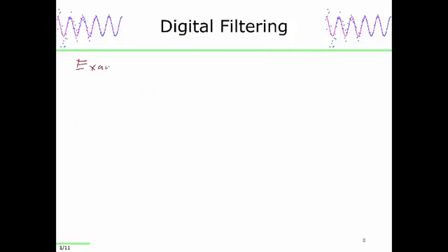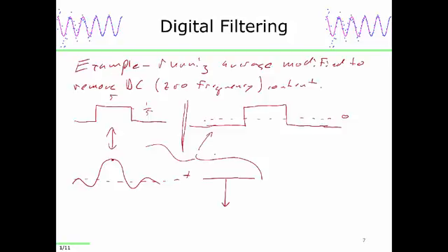How is the impulse removing the DC? So the question, well, okay, let's go over this a little bit. I'll give you a better example in the next slide, because this one's a little tricky. Because the time domain response is constant to begin with in the rectangle, and I'm subtracting off a constant, which would just give me 0, which would be nothing. So I have to make it longer such that the average of the digital filter is 0. Why would that matter? Because let's say I had a constant term, a background term. If I sum up every element in this digital filter and it equals 0, and I multiply that by the DC, it removes the DC.